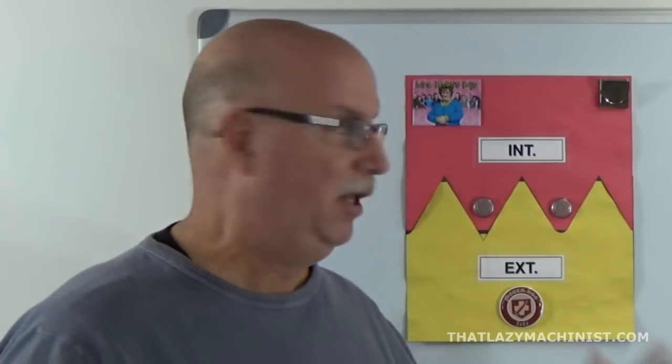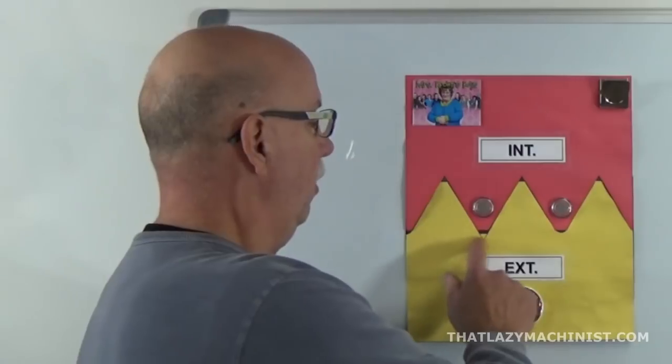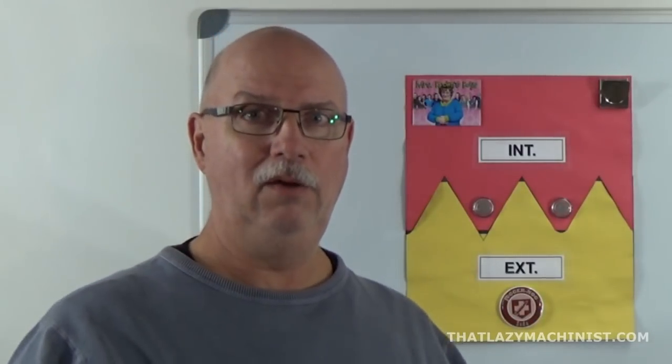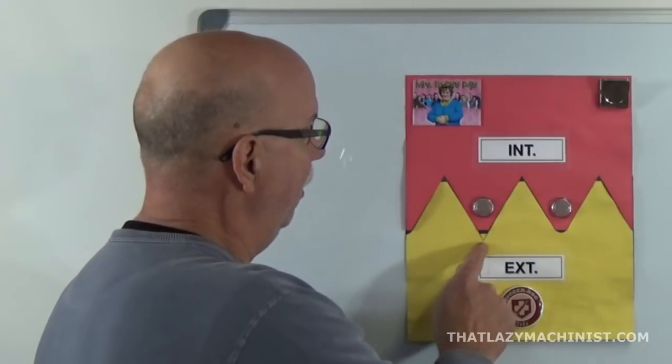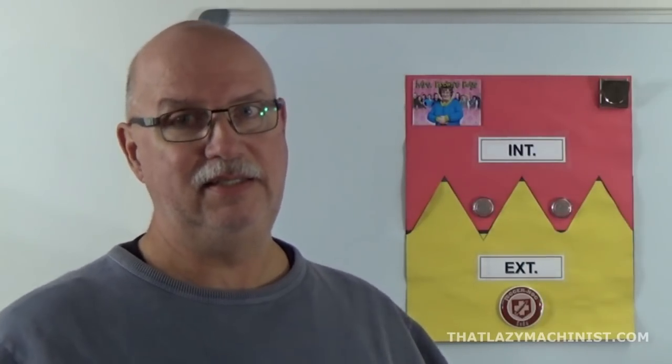Another term that I hear quite often is sharp V threads, and that needs to be clarified. Now, our thread form here has either a rounded root or a flattened root. Round or standard root. That's what exists, and that's what's possible. But we could have, and we see it here, a V that comes to a point, and that would be a sharp V thread. And that doesn't exist in reality.